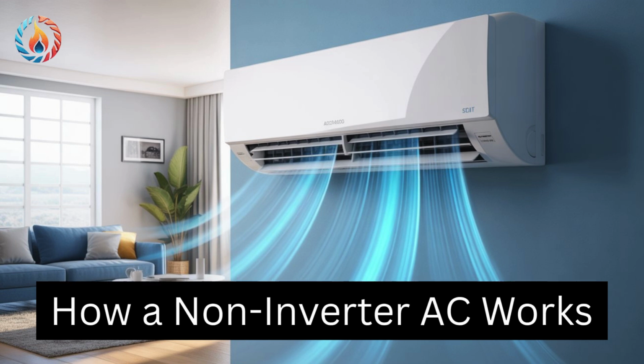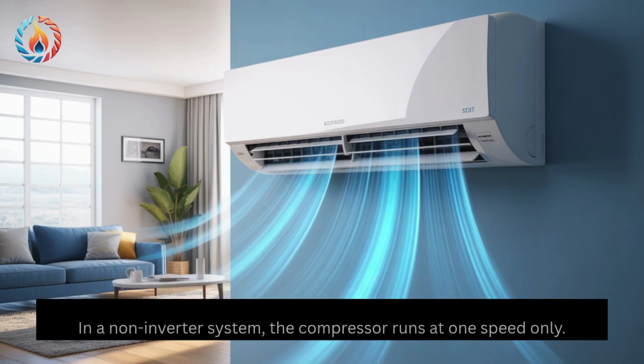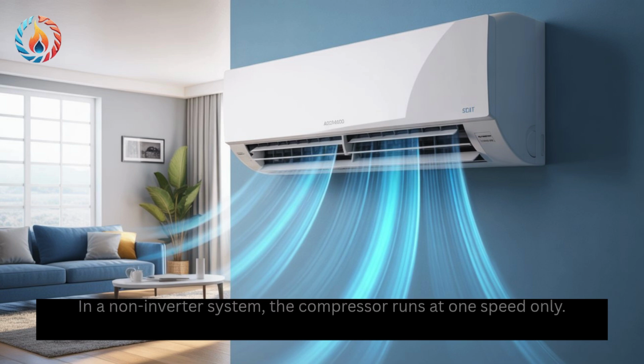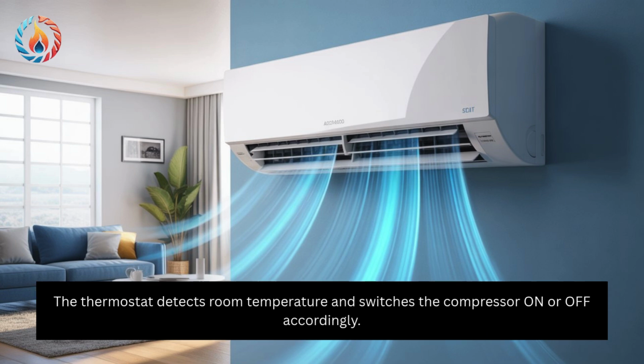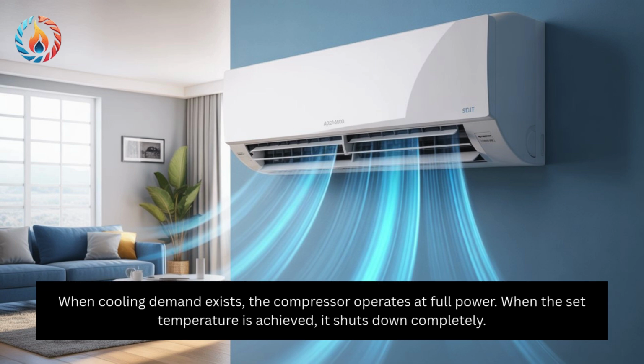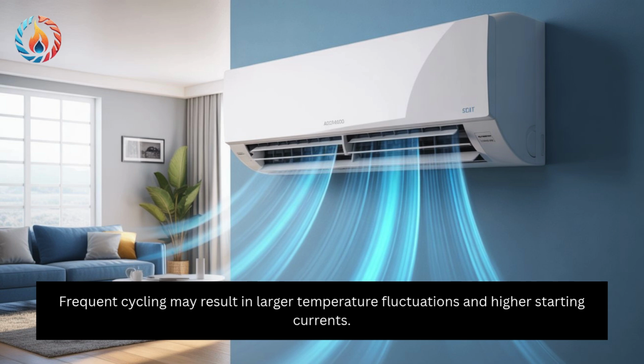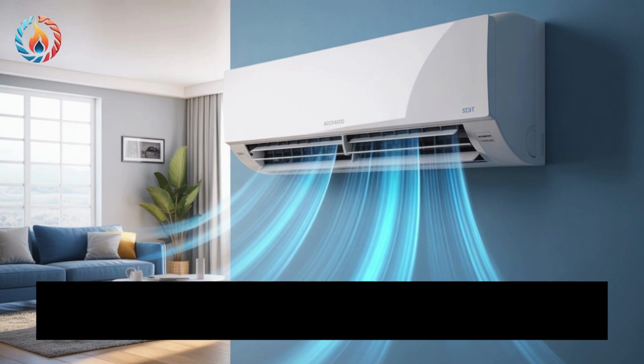How a non-inverter AC works. In a non-inverter system, the compressor runs at one speed only. The thermostat detects room temperature and switches the compressor on or off accordingly. When cooling demand exists, the compressor operates at full power. When the set temperature is achieved, it shuts down completely. Frequent cycling may result in larger temperature fluctuations and higher starting currents.